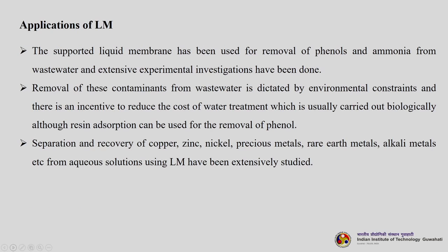Now, let us discuss the different applications of liquid membrane. The unsupported liquid membrane has been used for removal of phenols and ammonia from wastewater, and extensive experimental investigations have been carried out. Removal of these contaminants from wastewater is dictated by environmental constraints, and there is an incentive to reduce the cost of water treatment, which is usually carried out biologically, although resin adsorption can be used for removal of phenol. Separation and recovery of copper, zinc, nickel, precious metals, rare earth metals, alkali metals, etc. from aqueous solution using LM have been studied extensively.